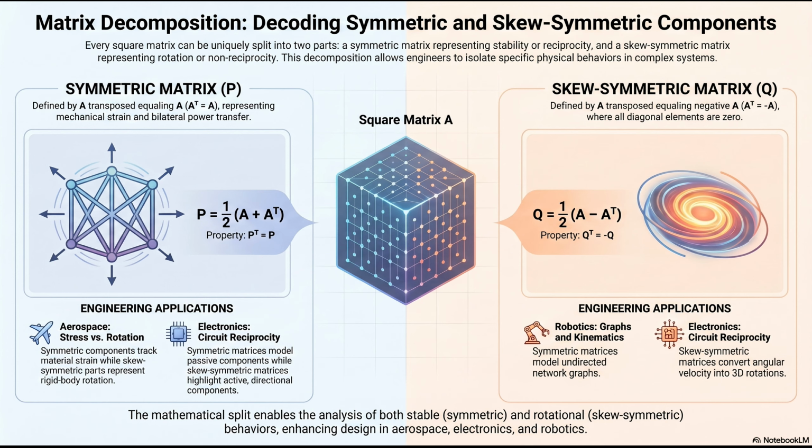Right. So by forcing the angular velocity vector through a purely skew-symmetric operator matrix, the kinematics engine mathematically guarantees that the distance between any two points on that robotic arm remains perfectly constant while it spins. It basically preserves the rigid geometry of the object during movement.